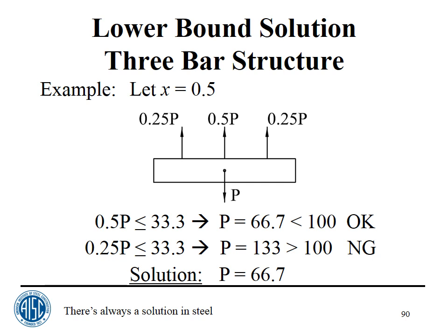If you actually built the structure like your wire diagram shows it, you would satisfy all three principles of structural mechanics, but you don't build it that way. There's no way you could actually make that work. So what I said before was, if you think the loads in your structure are exactly what you think they are from any fancy computer program you have, I'm saying no way, because the structure is not built like the model assumed it was.